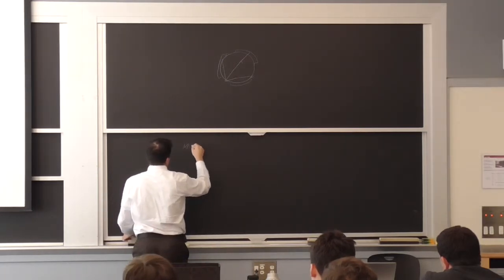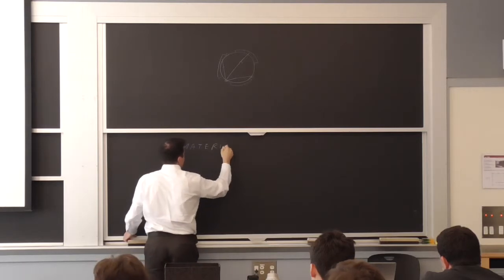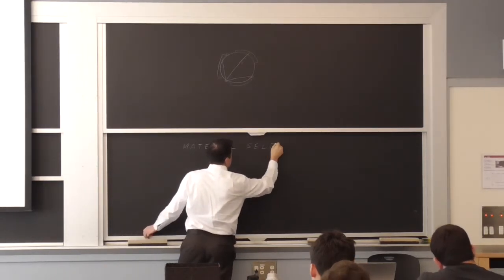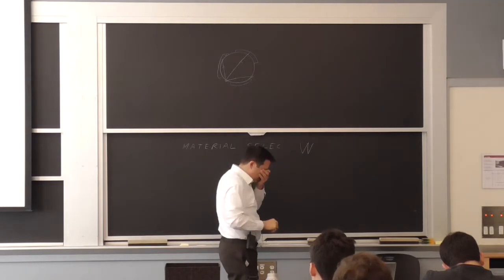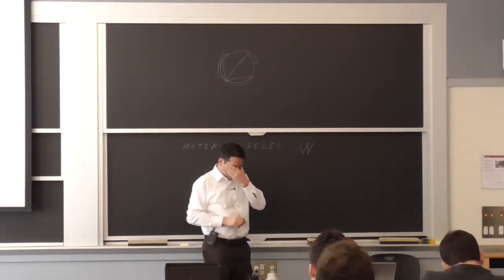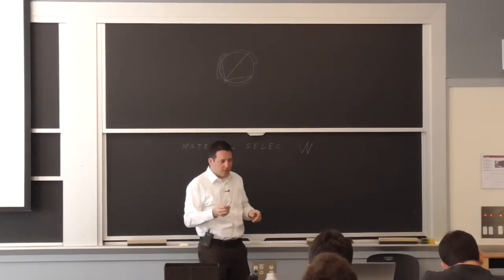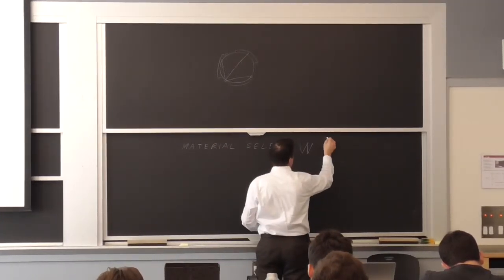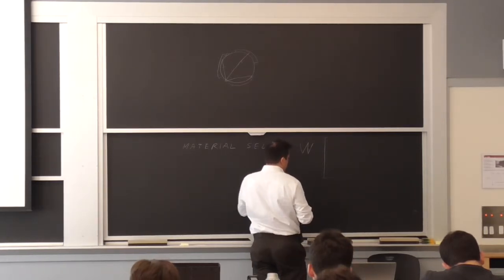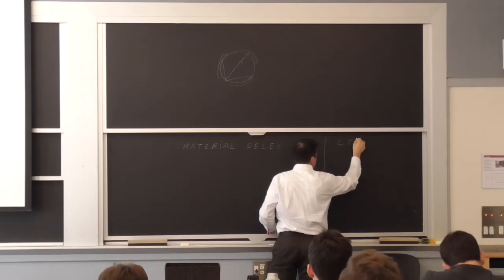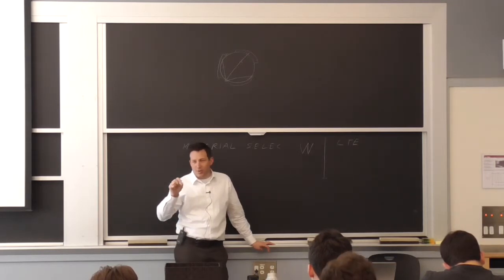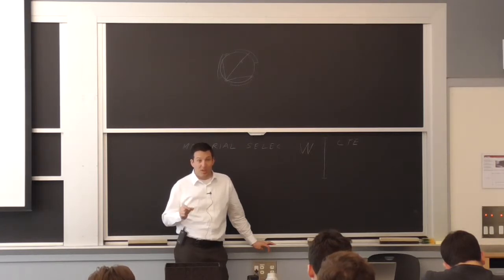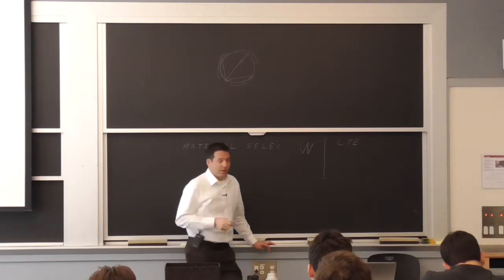So the material selection. You can use tungsten. It's a good fusion temperature, although if you look at what are the characteristics? When we talk about thermal expansion here, there are a few characteristics we're interested in. I'll call it the coefficient of thermal expansion. One reason that's important is this little layer of tungsten is sitting on a block of copper, because copper is a lot more conductive. So you have to be able to match these coefficients close enough.